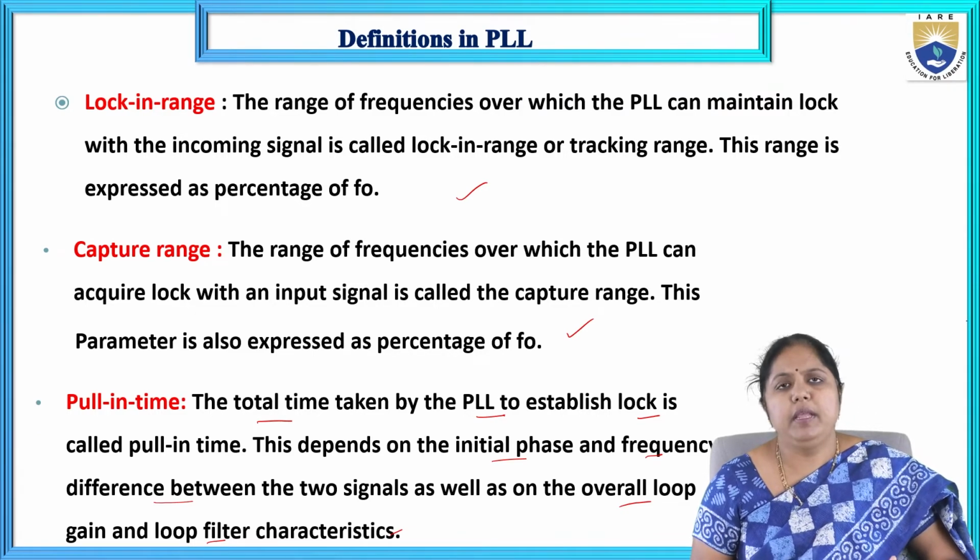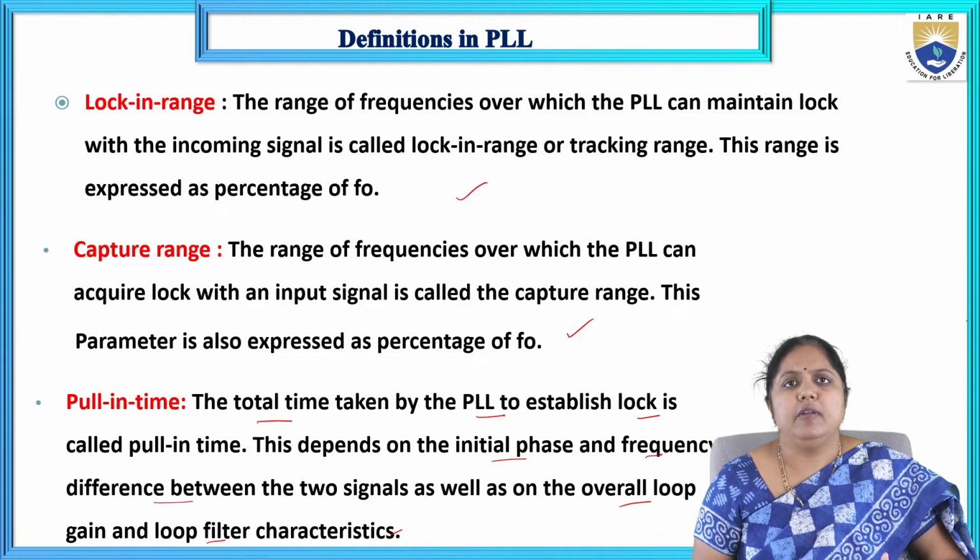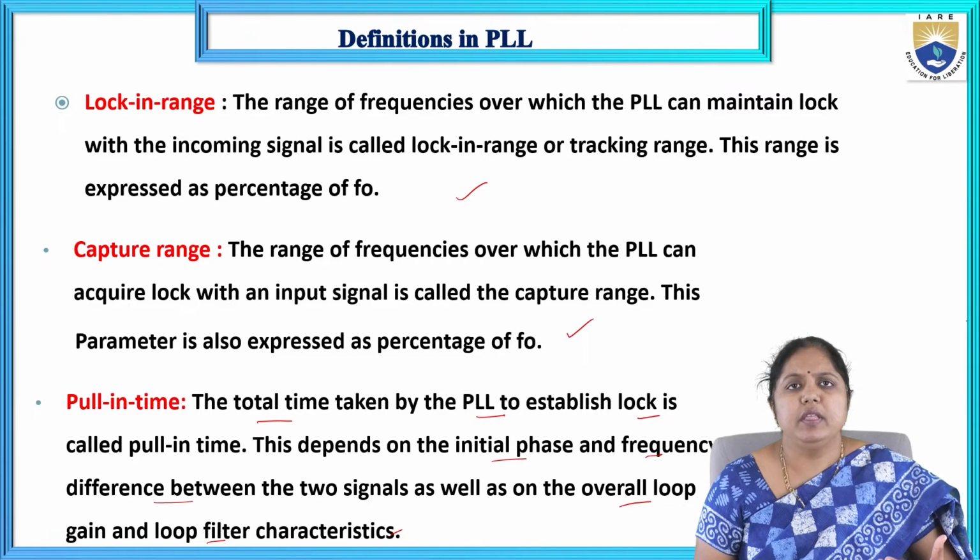Okay, so what is the basic function of the phase detector? The phase detector is a free running multivibrator which works as a comparator, comparing the input signal frequency with the VCO output frequency. Based on the difference, it generates the output voltage Ve, which contains the sum of the frequencies, Fs plus F0, and the difference of the frequencies, Fs minus F0, at the output of the phase detector.